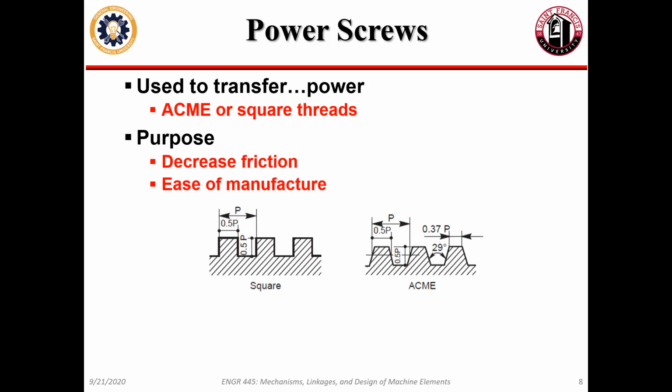So as soon as you start to taper them, you increase the amount of friction between the bolt and the thing it's mated into. If I'm putting a fastener into something, say a screw into a hunk of wood, I want friction. That's why screw threads have a very aggressive thread angle, usually a 60-degree thread angle.